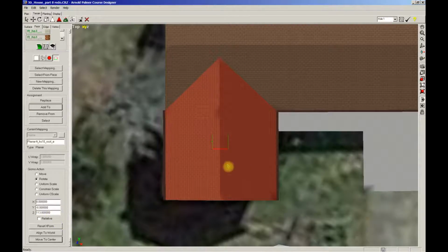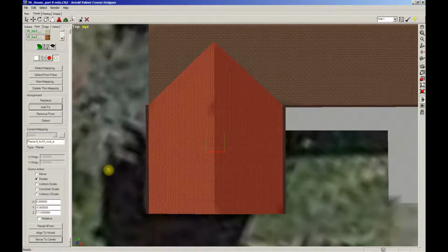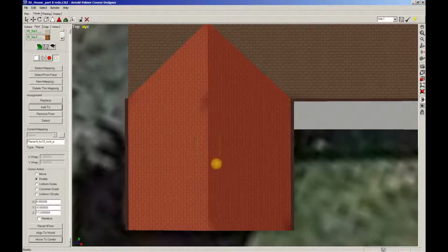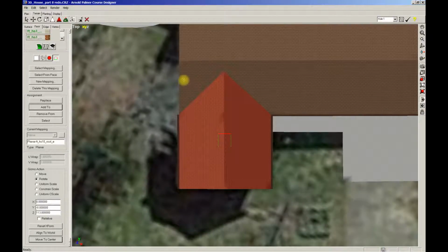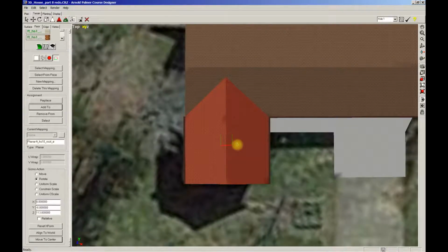I just turned it and shot it this direction. So this is the way I want them lined up. If you can remember, any of your windows or doors that face east will always be set to 113 to square them up properly to start with. So you don't have to mess with trying to move this thing around by hand and get it perfect. This will get it right where it needs to be instantly.